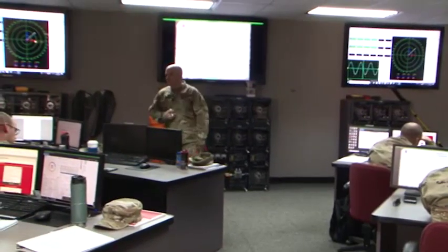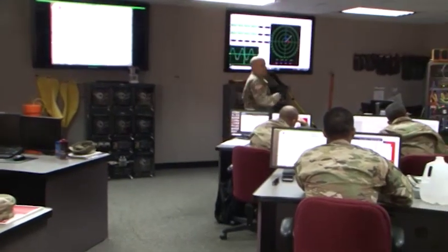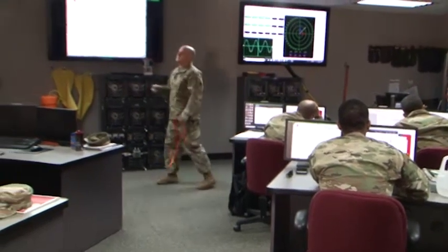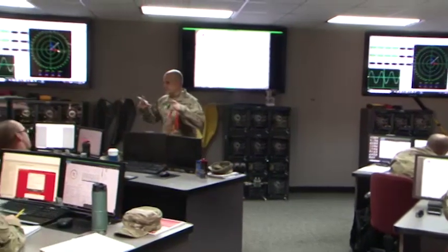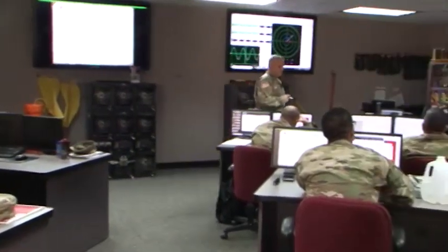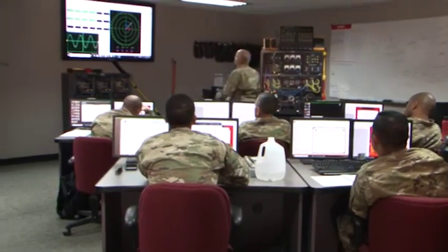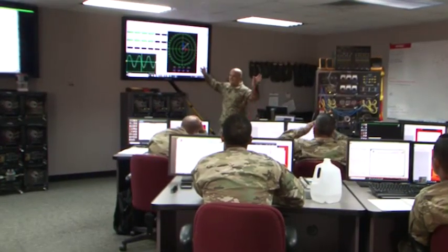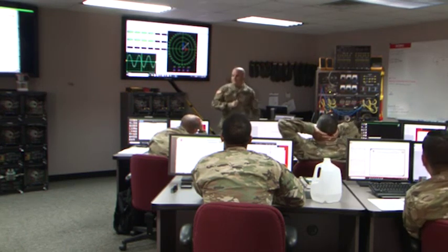So if you had an RLC circuit, and we added a capacitor in series there, and you can see this in the formulas in your book, it's going to be the square root of R squared plus the quantity of X of L minus X of C, squared. So the difference of those two, right? Kind of pulling this way, whatever you're left with, squared, is going to equal your impedance. So we just did all of that. We confirmed it, and now we see too these voltages here, two different voltages. There's an angular difference between the two going across these loads, and now we're left with some resultant thereof.